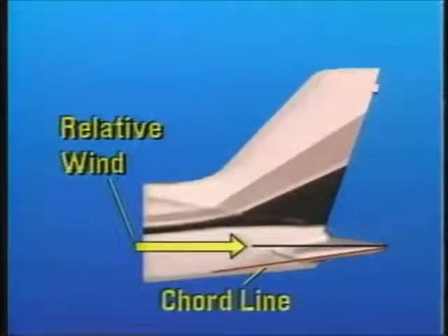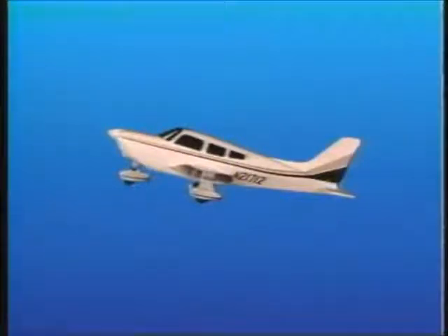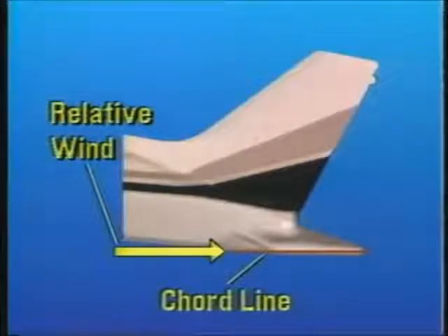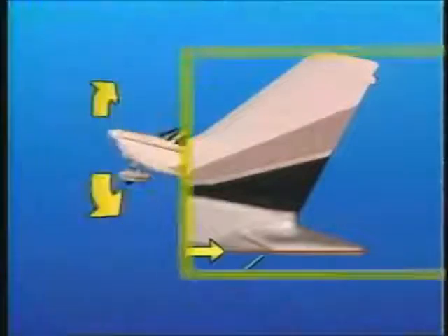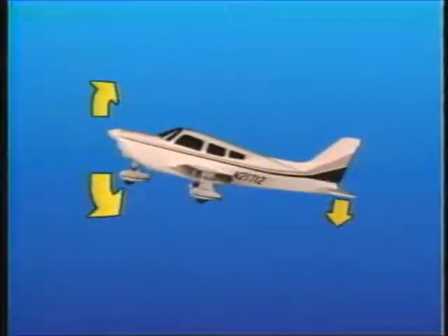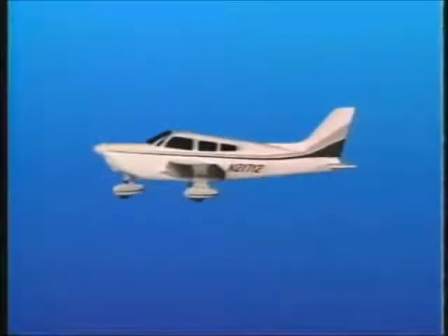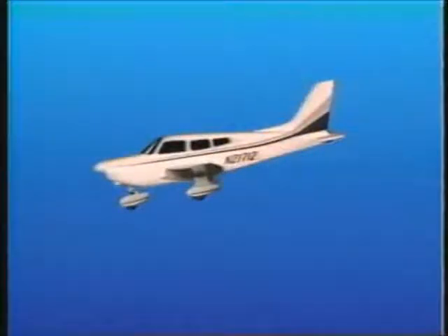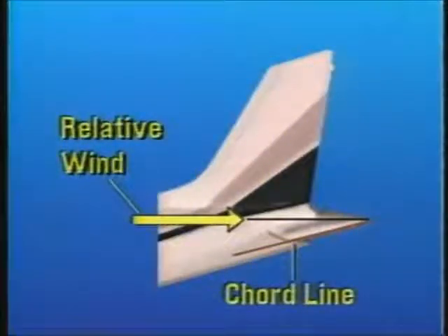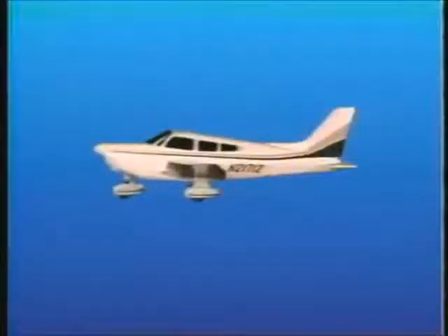If your airplane pitches up because of a gust of wind or momentary control deflection, the horizontal tail surface moves toward a neutral or slightly positive angle of attack. This decreases the tail-down force, and because the nose-heavy condition is no longer balanced, the nose will return to the trimmed condition. Similarly, if the airplane pitches nose down, the negative angle of attack, and in turn, the tail-down force increases. This tends to return the airplane toward its trimmed attitude.